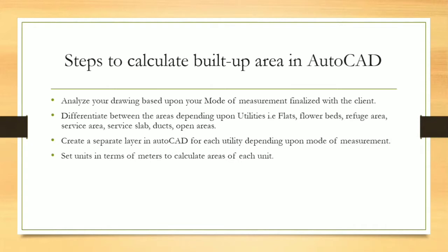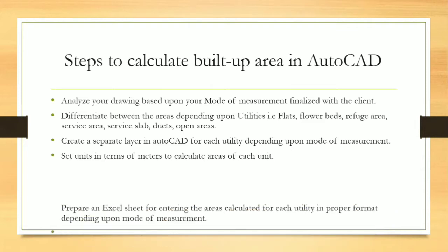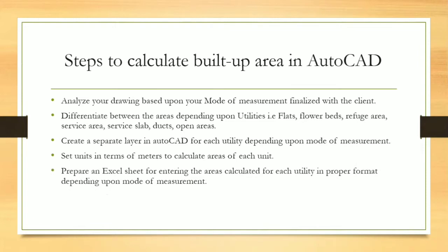The next step is that we have to set our unit in terms of meter. We will see in AutoCAD how we can change our unit to meters, because calculation of area in meters becomes very easy and we know the direct conversion of square meter to square feet. Now, if we want to present our built-up area in some kind of meeting, means we are not just verifying, we have to give one built-up area statement to someone, then we have to prepare a proper Excel sheet of the areas calculated of each utility in proper format.